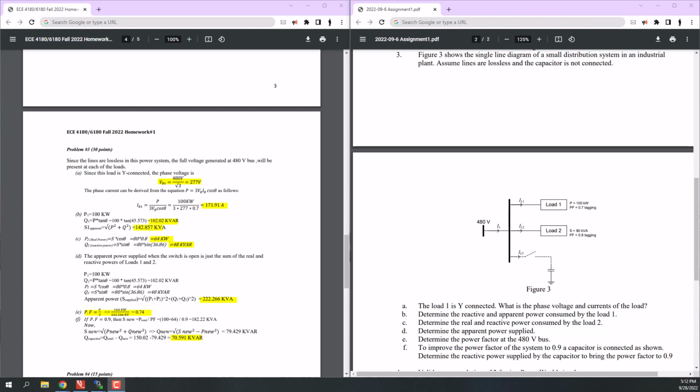First of all, we always have to be careful whether the question is asking about phase voltage or line voltage. In this case, it is phase voltage. When we calculate the voltage here, and we only have the voltage at this bus, if we name this one V1, V1 would be V0 minus the impedance between those lines multiplied by the current.